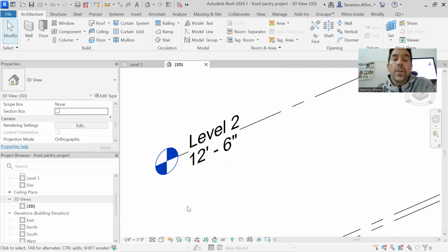The classic question sometimes is, well, if I'm doing a little section of my project, yeah, people are coming there, but it's not the whole floor. Well, it is a place where people can step on. That's called a level. You might create it. But even if people cannot step on, maybe you have a particular item protruding from your wall at a specific height, for example, to block the sun from coming in. It's a horizontal item and it's quite prominent enough for you to use levels.